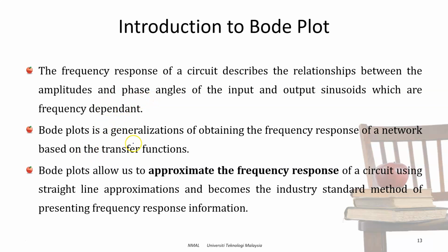So I repeat, it is a generalization of obtaining the frequency response of a network based on the transfer function. This transfer function is the relationship that we described between the input and output sinusoids in terms of amplitudes and phase angle. Bode plots allow us to approximate the frequency response of a circuit using straight line approximations and have become the industrial standard method of presenting frequency response information.